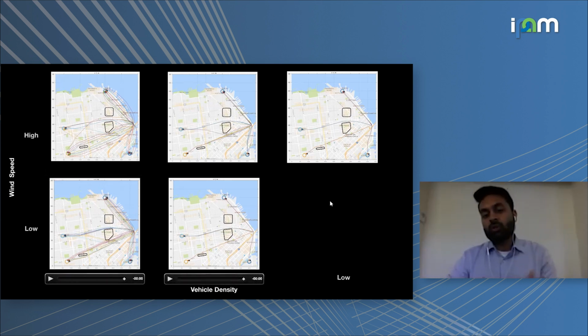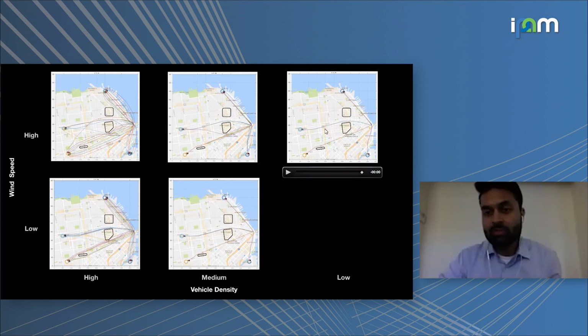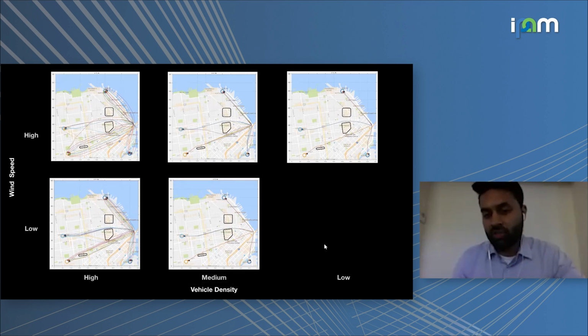That's to make sure that in the presence of high disturbance, any 2 vehicles are far apart from each other such that they don't collide even in the worst case disturbance. But the nice thing is that we never hard-coded any of these behaviors, these multi-lane behaviors or this lane-splitting behavior. These behaviors emerge automatically out of the Hamilton-Jacobi reachability.